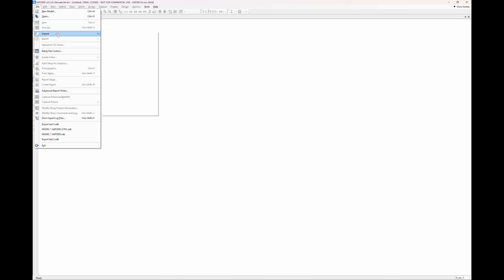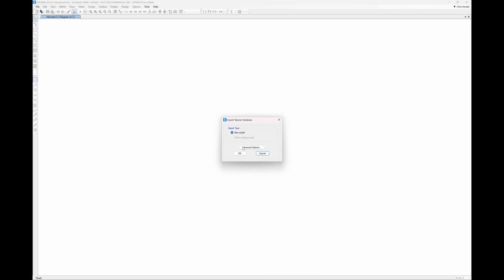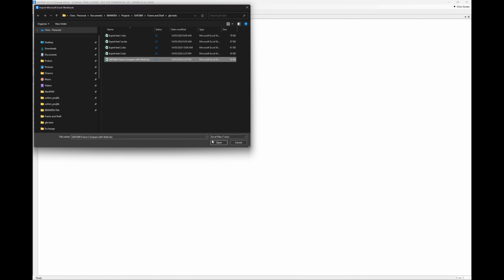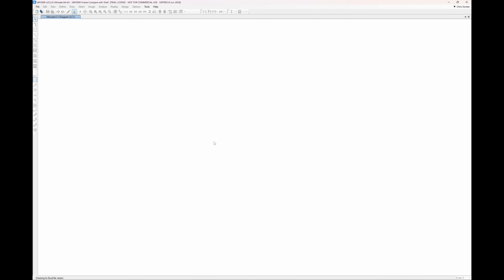So once it's done, we can go to SAP 2000, go to import MS Excel spreadsheet. And when we click on OK, oh well, we're just closing the current model. But when we open up that SAP 2000 Excel spreadsheet, it'll take a little bit of time to process, but you'll see at the bottom left there, it's checking the user-defined sections and field names, etc. So when we export to SAP 2000, we actually generate custom section profiles for all the sections exported from GenFEA. This is important because it means it'll always work regardless of whether they are mapped between the two software packages.